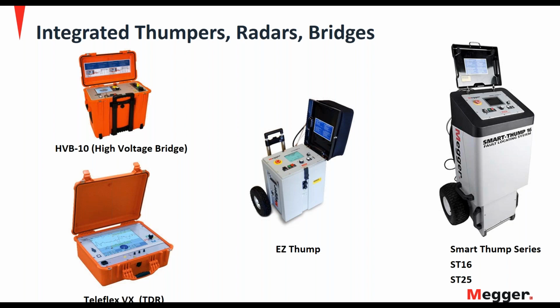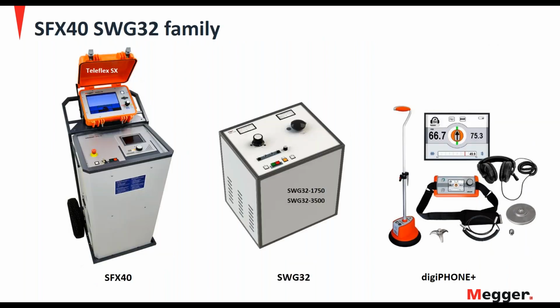A high voltage bridge is a different method, other than arc reflection, to get a fault distance. Here we have some non-integrated thumpers. These are usually larger units. You can see how you could utilize a radar with them. On the SFX40 here, there is a radar that's associated with that.